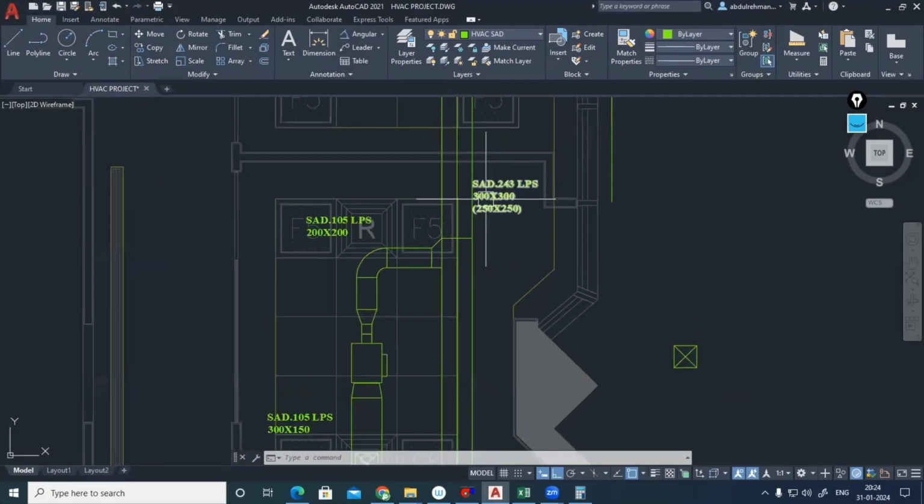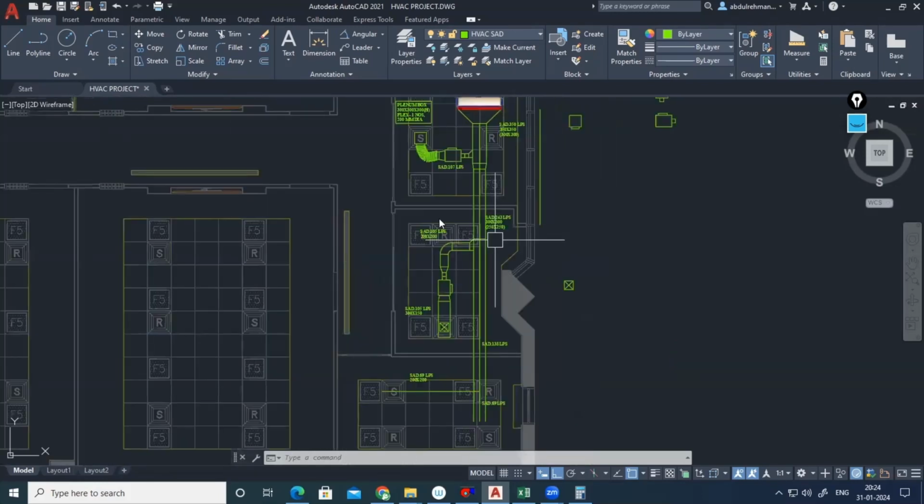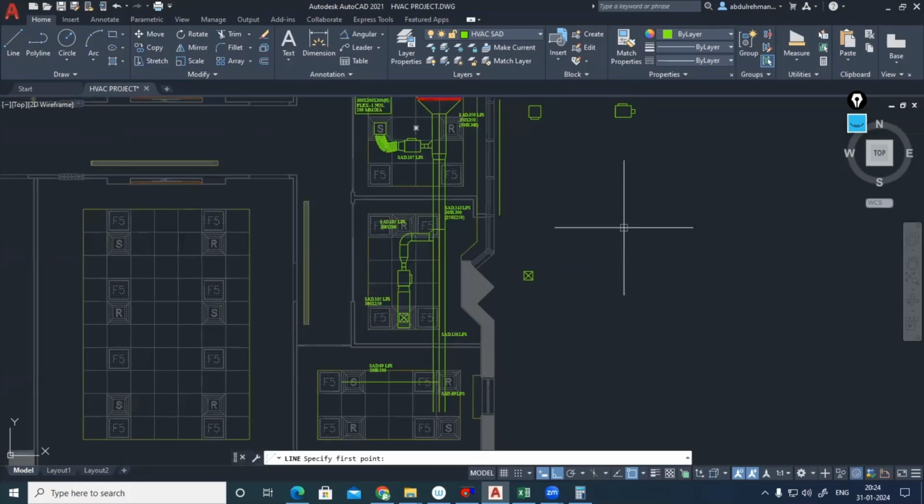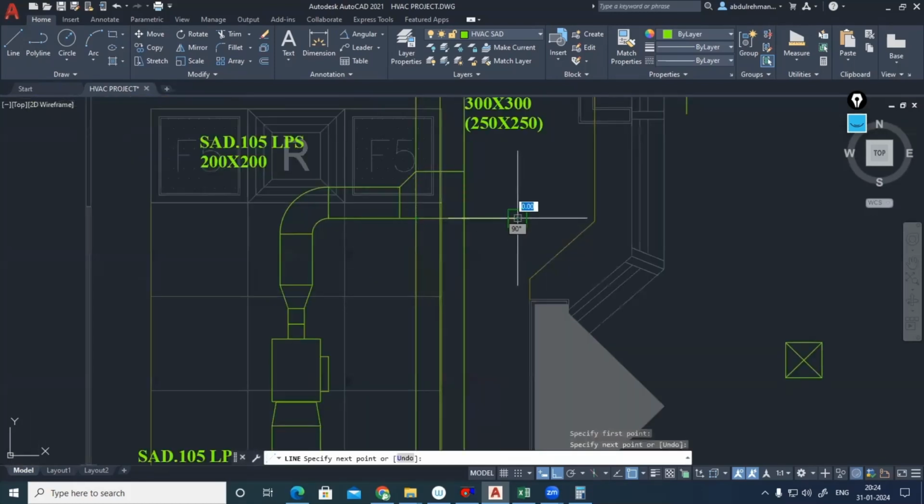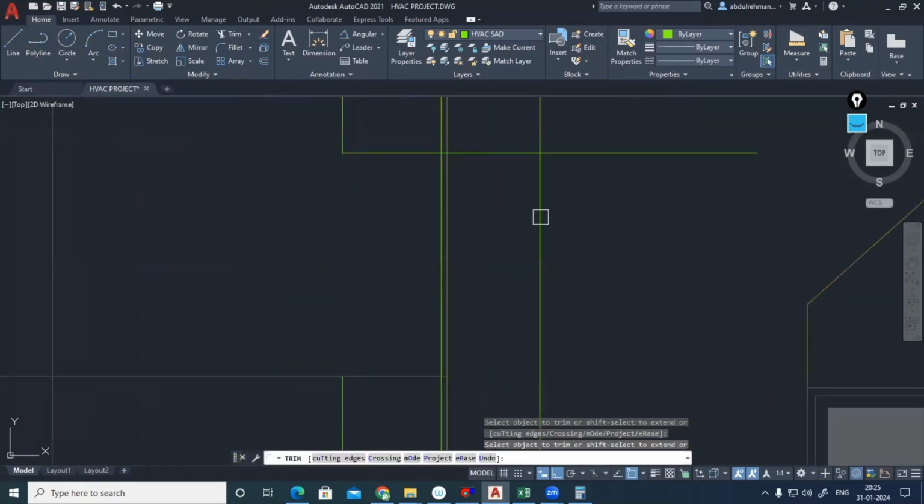Definitely, but the external dimension is 300, no? So we have to make it 300. We have to make it into 250, 200. Yeah, sure. There is no other option because external is 300 only. So I'll be making a dimension there. Offset it. Enter, I'll be offsetting this into 150 mm. Okay. Now just trim it at TR double enter. Unwanted lines you can trim.